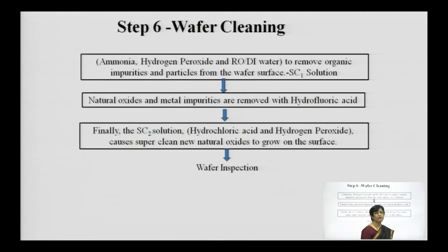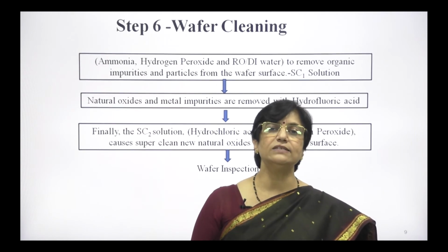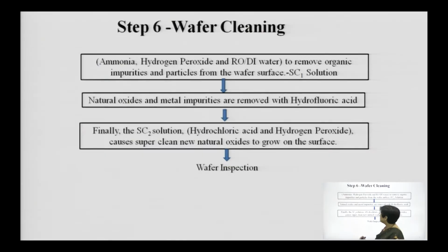Once polishing is done, cleaning. Cleaning also happens after every stage. We have seen cleaning once prior to our lapping, and post etching, after the lapping, we did etching and at that time also we cleaned our wafer, and now also we are cleaning the wafer. Generally it is called RCA cleaning, and it is performed in 3 stages.